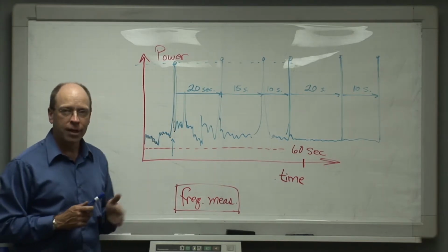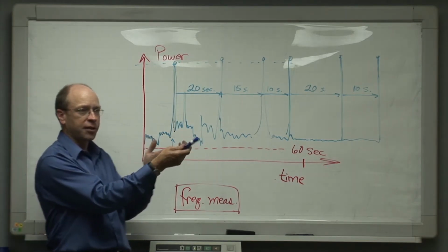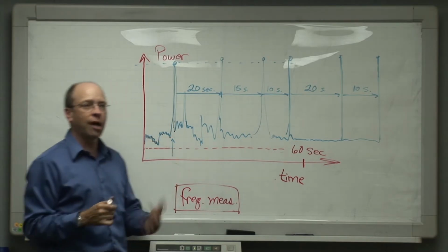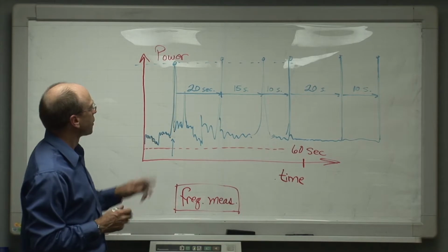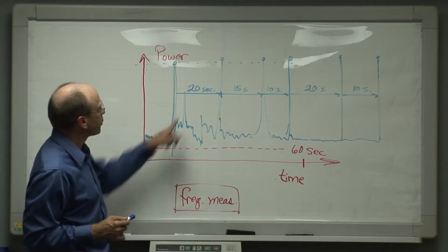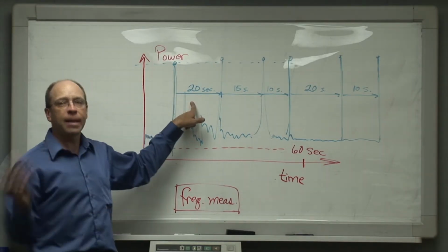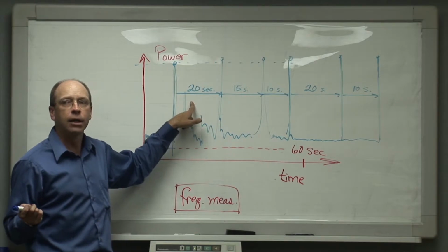Which, interestingly enough, is the interval for a long-range air search radar if it's simply rotating mechanically. It's the same problem. They don't want to not look in a certain direction for more than a certain amount of time before they look again. So they say, oh, so suppose we want to measure this radar with the stepping algorithm we just talked about.